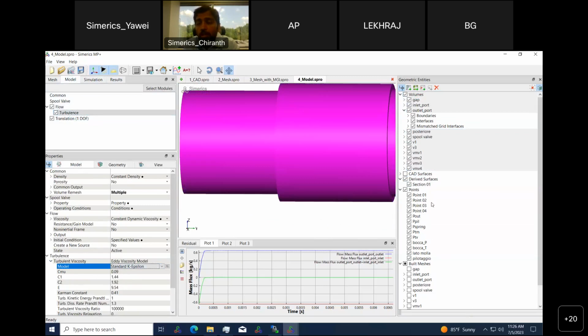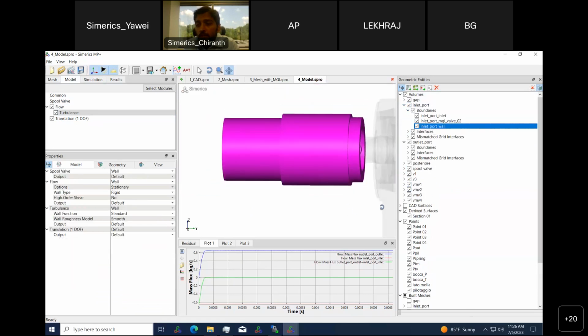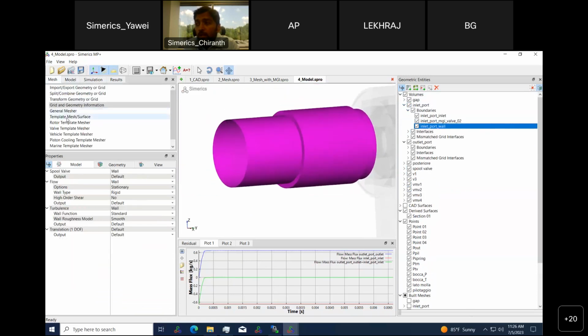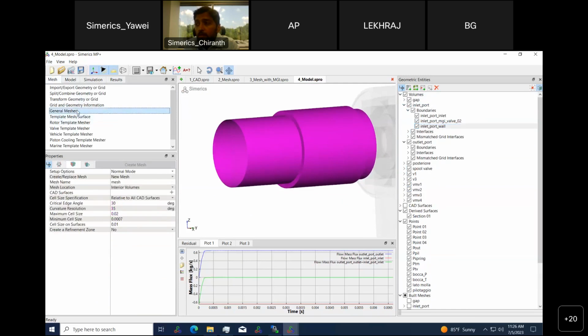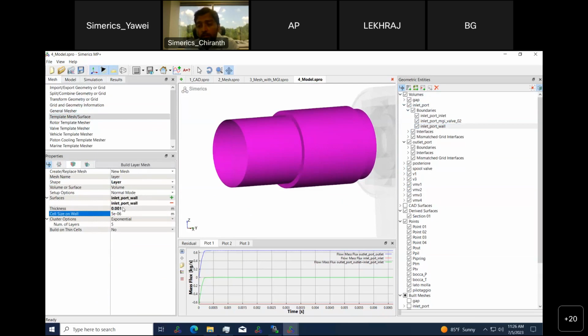We have one capability which is we can add prism cells on the boundaries which can grow out of the boundaries. Essentially you have to add it to the boundaries. So that is a capability in case we do find some applications where we need the boundary layer mesh. In that case we use that, but we need to push the cells in a little bit before you grow it so that your size is still maintained, basically.